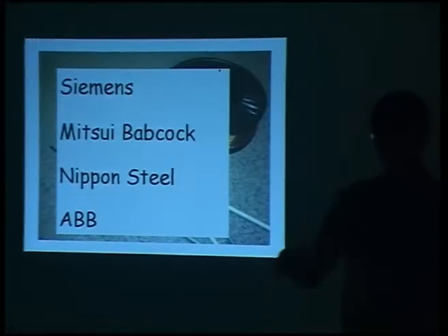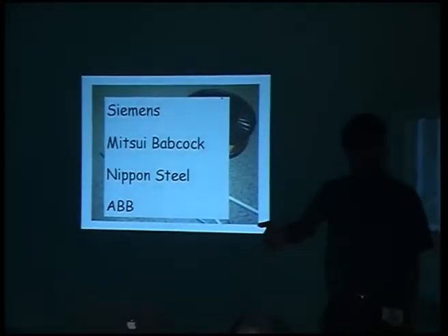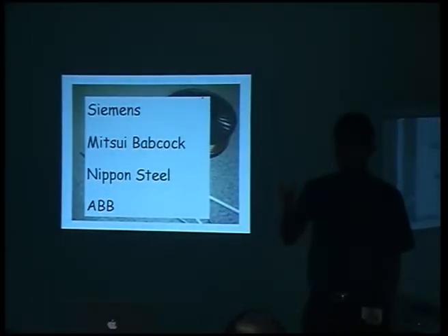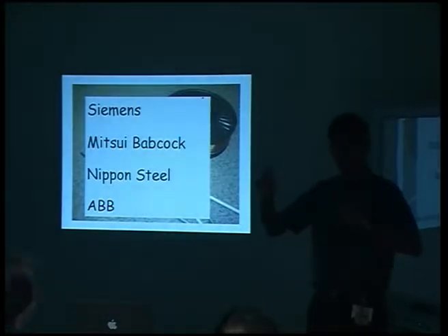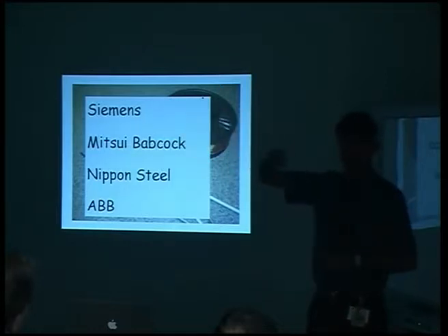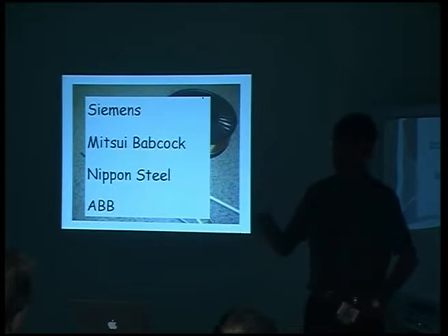And you know that lasers are becoming much cheaper. So diode lasers are coming in, and the normal robots that are used for making resistant spot welds are really huge, and they have clamping forces and so forth. Whereas if you had a laser, you could just pipe the laser beam with an optical fiber, use a small, very agile robot to do the work.